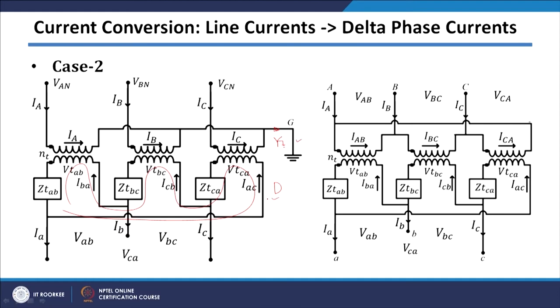If you see the second example here, I am considering a delta connected transformer. So, on both sides at the line ends there will not be zero sequence current because there is no ground terminal at both ends. However, whenever there is some zero sequence current flowing through the delta winding, which is basically a circulating kind of current, then there will always be a balancing zero sequence current flowing in the other delta. So, it is basically these zero sequence currents that only flow in the delta windings on both sides.